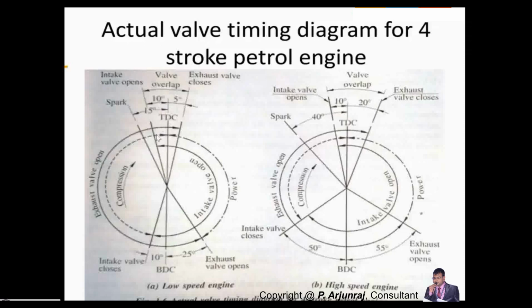You see here, the inlet valve opens 10 degrees before top dead center. And then what happens is, after the air fuel mixture comes in, the inlet valve closes. This inlet valve will close 10 degrees after bottom dead center. This is the after one. This is the before one.